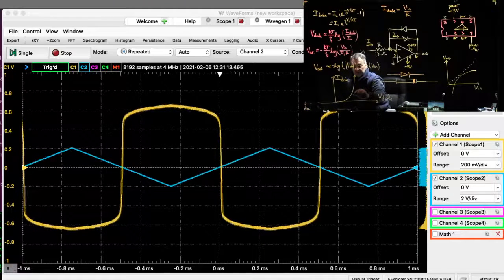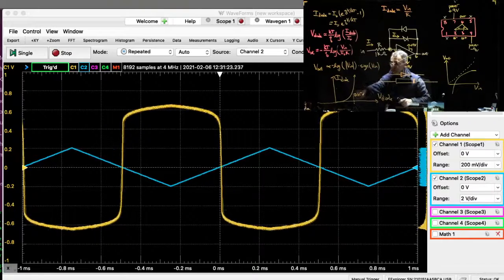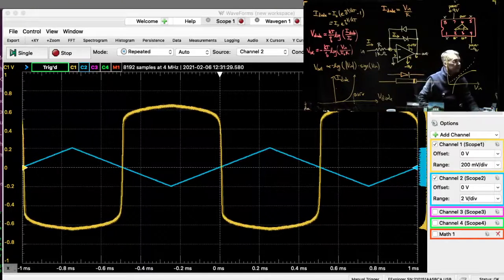So this is our diode drop region, right? This is maybe 0.6 to 0.7 of a volt. Once the diode starts to turn on, you should be in this steep region, in the 0.6, 0.7 volt region. That makes sense, because once we get any significant current through the diode, we're getting close to the 0.6 volt range. But once the diode is on, the voltage increases very slowly as the current gets bigger. So it's relatively flat here.